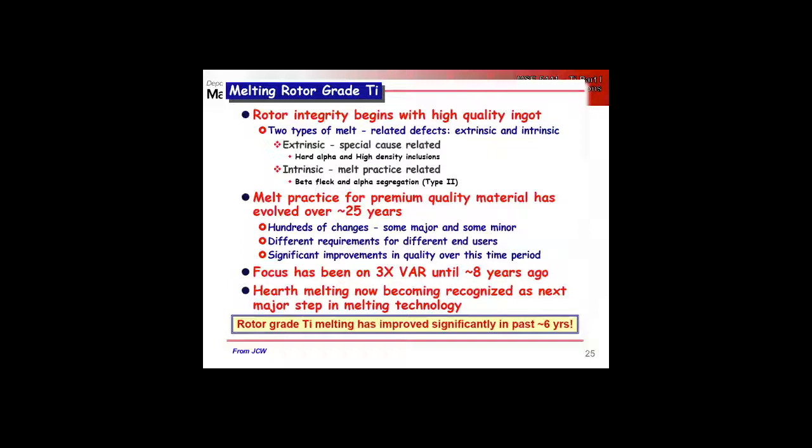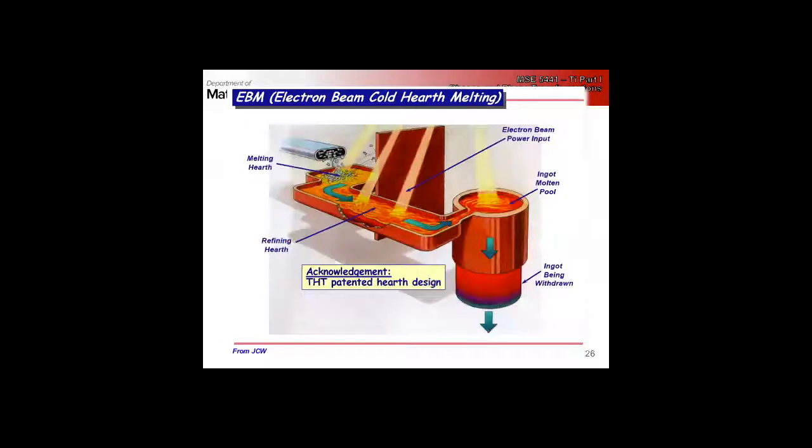It's pretty cool how titanium is actually processed now. The key advance was this hearth melting technique. Basically, you've got a channel where the molten titanium flows. This is all done under vacuum. Even if you didn't know anything about the process, how would you know that this is under vacuum? Well, besides that, the Ellingham diagram for titanium is pretty telling. But if you didn't know anything about what metal this was, how do we know it's under vacuum?